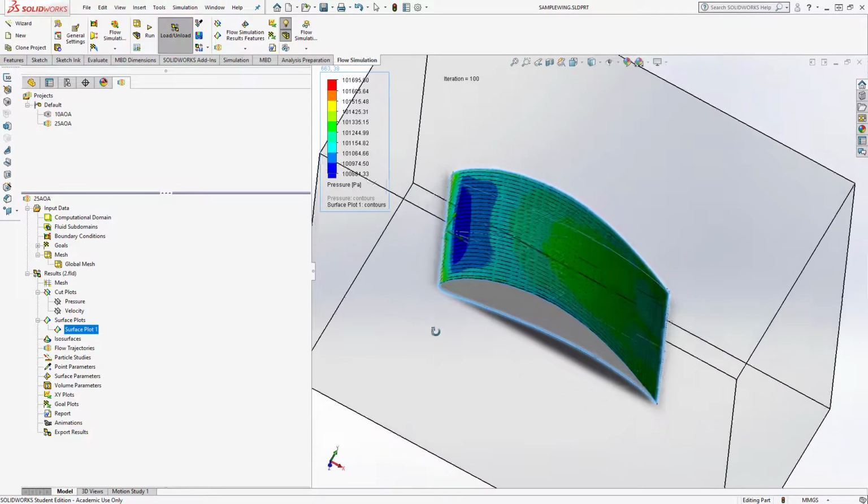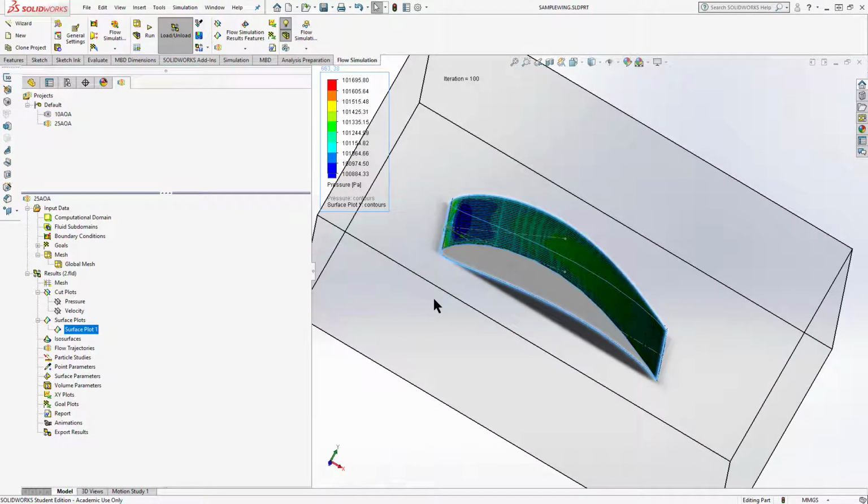Now, we didn't really see fully developed stalls on any of our wings, and the reason that we didn't see those in the wind tunnel was we were only flying up to about 50 miles per hour, so that we didn't have failures of a mount point. If we were to fly those wings faster, we would be able to develop full stalls on them. So as it is, our laminar flow stayed pretty consistent all the way up to 25 degrees angle of attack, simply because we had such low airflow over it.